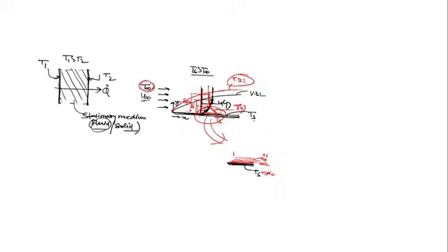So this causes a temperature gradient in the fluid. The temperature gradient in the fluid occurs here. It means the temperature decreases like this. Yes or no? As we move in the y direction, the temperature decreases like this. So this causes a temperature gradient in the fluid. So the temperature gradient occurs. It means if you see, there is dT upon dy. Yes or no? Just like in momentum transfer, there was a velocity gradient. Any fluid that comes to the surface will come to rest, but any other fluid just above that will be in some motion, will have some velocity, and that causes the velocity gradient, and that causes momentum transfer.